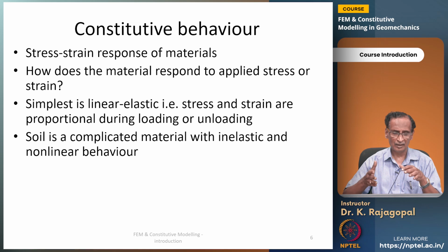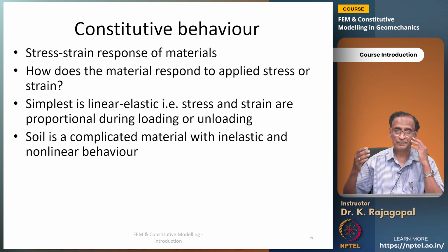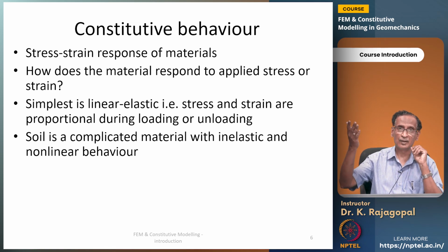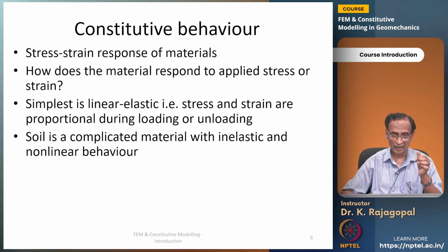And then the soil is a highly nonlinear material. There is no one-to-one correspondence between the stress and strain, and also it is inelastic. That is, during loading it might behave one way, and during unloading it might behave in some other manner.